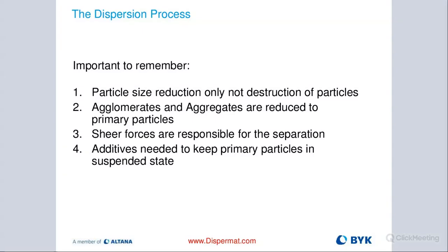It's not only about the RPMs, right? People always say, hey, I need a machine with really high RPMs. RPMs are critical because they get us to the right tip speed, but it's really more about the amount of energy that we are putting into our mill base that helps us to get there.